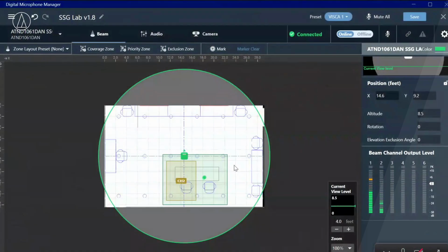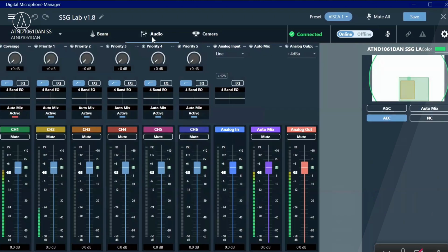Now, if you notice there, as we went back and forth, there were these 2 different audio channels that we were both on. So even though this is just one device that's up in the ceiling, we actually have 2 beams that are showing our audio. Now, what you're seeing right now is that channel 1. You can see it's the stronger level, and that's my voice there. And you can see it coming in a little bit into channel 2 because the way that our system works is it puts that other beam into a standby mode or an inactive state. It doesn't completely cut it off. You can if you want to, but it doesn't completely cut it off